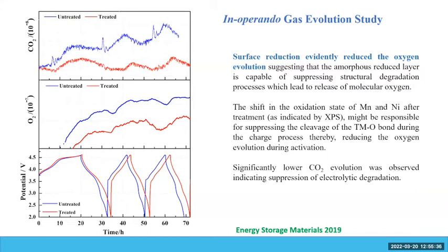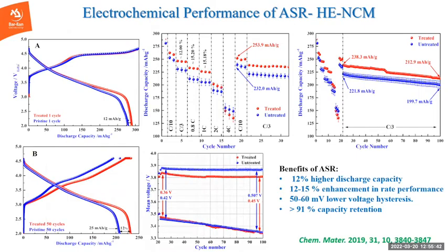When we go to the electrochemistry, we can see that the capacity is also improved. This is about twice the capacity you have of lithium cobalt oxide in the commercially available battery. And you don't really need to understand all the electrochemistry, but I want you to remember here, this is 4C. 4C means how much current I have if I'm trying to discharge my battery 4 times in 1 hour. Very quickly. I'm trying to discharge my battery 4 times its capacity in 1 hour, meaning trying to fully discharge my battery in 60/4, 15 minutes.